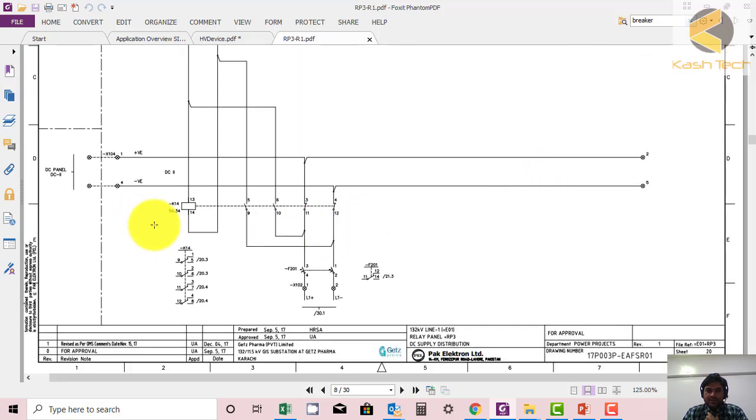Again, we are calling this an auxiliary magnetic contactor, or it could be an auxiliary relay. There is a small difference. Relay is a small transparent type and contactor is black and heavier. So you can check physically in the panel, but both function the same. So this is an auxiliary relay, we can say. And these are the contacts of this auxiliary relay.